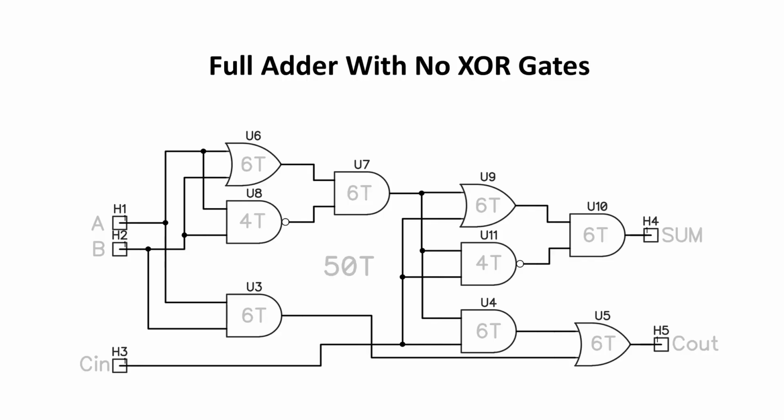So I'd end up having to have 4 boards. So 4 adder boards doing 2 bits each, plus the B control register, plus the B register and the A register, and the control register above it. That would be a total of, what, 4, 5, 6, 7, that'd be 8 boards high. So that's 0.8 of a metre. Makes the whole circuit a bit tall. These are making it a bit more rectangular.